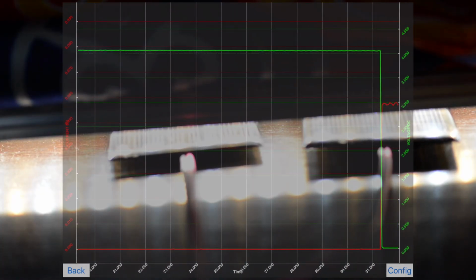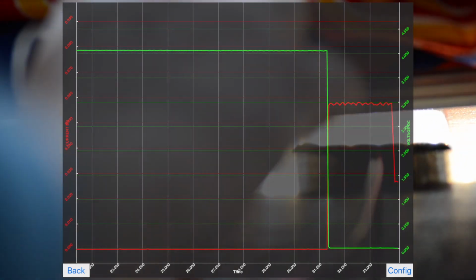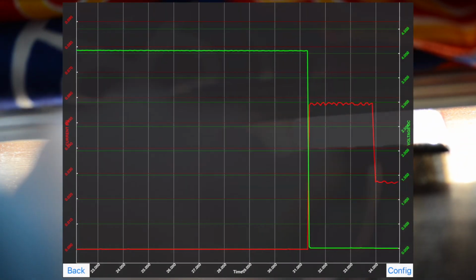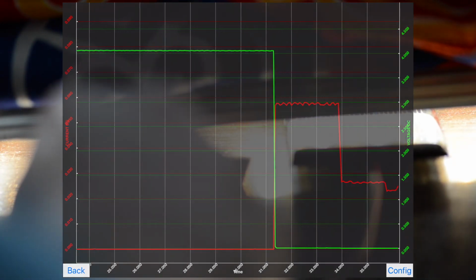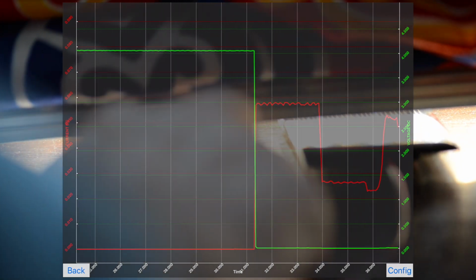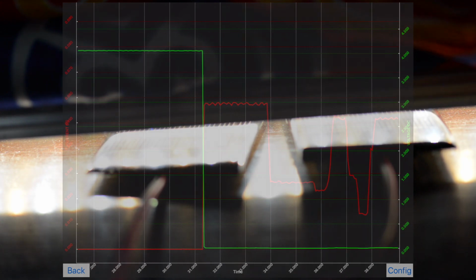Okay, so now I have the two generators in parallel, and right now they're an open circuit, and their open circuit voltage is about 4 volts. And now if I short them, voltage crashes, and my short circuit current is about 60 milliamps, which is double of what we saw previously, given that they're in parallel. If I pull one out, flip it on its head, you can see that the current crashes to about half, and that's because they're in parallel. Bring it back. So lower voltage, but double the current, or half the voltage and double the current for parallel configurations.